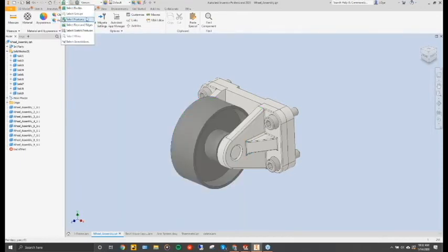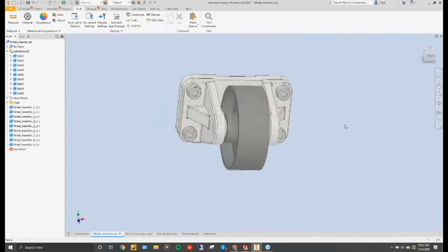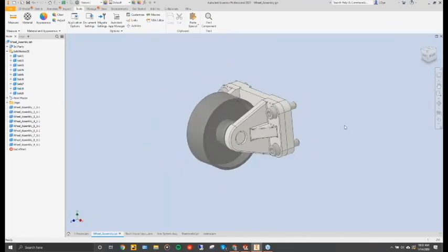So as mentioned, depending on what you have the filter set to, faces and edges, select features, select bodies. So I do select bodies, just make a window around that. And I'm only selecting that socketed cap screw, okay? Because I'm fully encompassing those components. There's those two socketed cap screws. There's that pin inside that wheel there. So I'm only selecting that pin now. So in previous releases, you weren't able to independently select the individual bodies by making a window around there. And that also goes for faces as well, if you have the filter set properly.